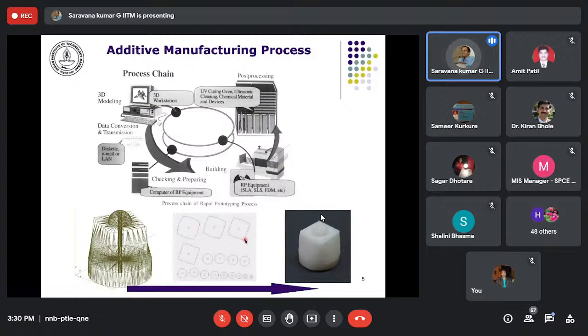It slices at about 16 microns. So you can see that when you slice at such small slices, pretty much the deviation in the profile that causes this surface roughness and deviation from the actual geometry could also be minimized.